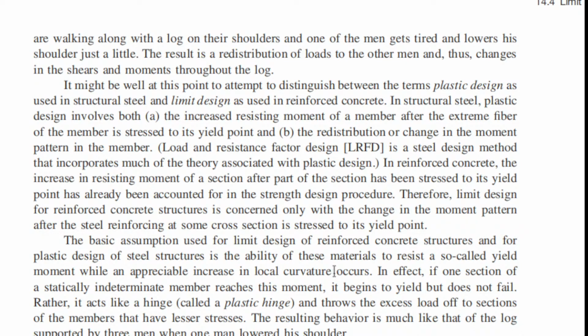So you can draw your force diagram, your bending moment diagram, then your curvature diagram, then your deflection diagram. So there are at least four diagrams that we need to draw in order to imagine the effect of the load.